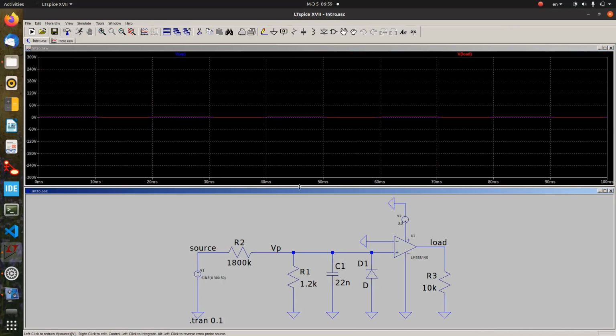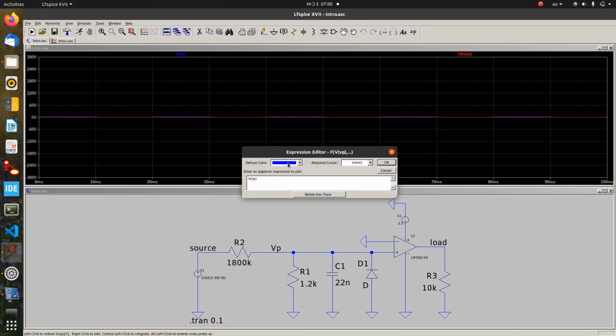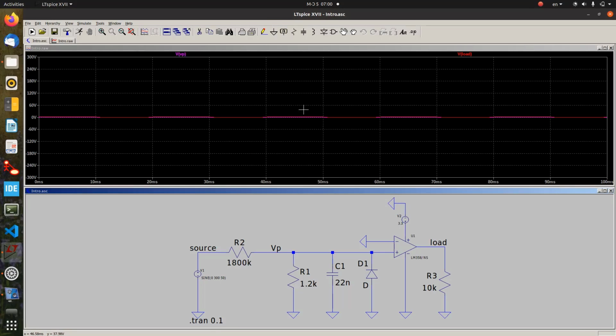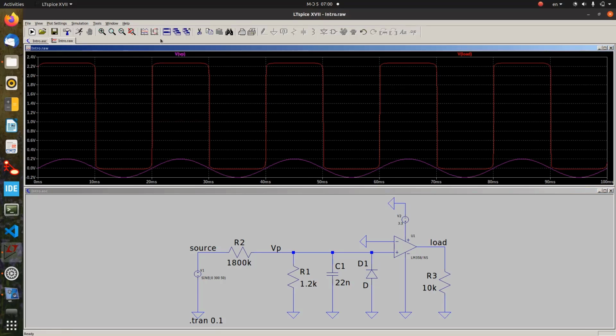Alright, so let's use this method to actually get rid of it. Delete trace. After deleting, I can see that the amplitudes for the remaining waveforms are very, very tiny and not really visible. So what I can do is click on this graph here and then click on the auto range option. That sets up the range for the plot, the vertical range.